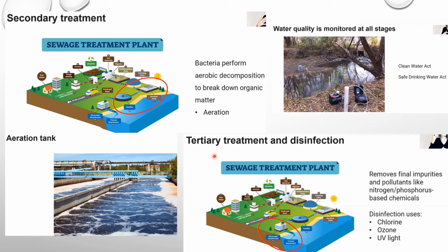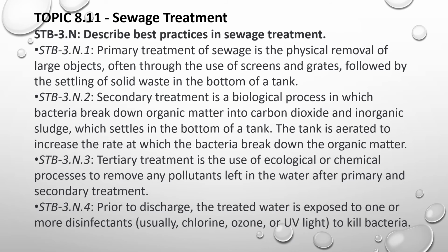And then we move on to our tertiary treatment. And remember I said tertiary is going to be like that ecological and chemical piece, okay? So they remove other impurities and nitrogen and phosphorus-like chemicals. And then it goes on to disinfection with chlorine and ozone and/or UV light. And then, of course, last but not least, we do the monitoring of the water and what's being discharged out of those point sources.